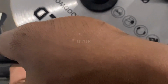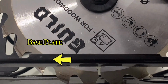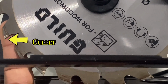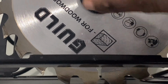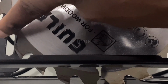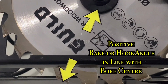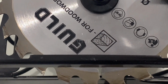And here you can see that the blade, which is usually protected by the lower blade guard, extends below the base plate. And you can see that the blade has got large gullet sizes between each tooth. The ATB, or the alternate top bevel, is suited for ripping. The 24 teeth is suited for ripping, but it essentially isn't suited for cutting strips from hard plywood. So we can see that this ripping blade has got a positive rake angle of anywhere between 0 to 20 degrees, and that's because you can see the inclination of the teeth.